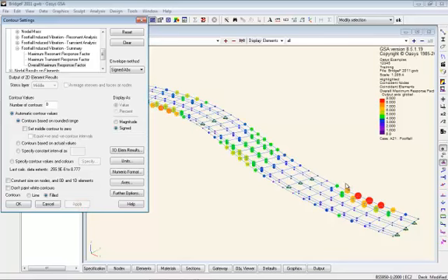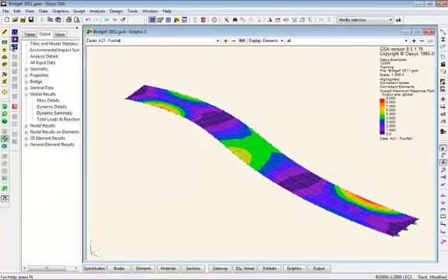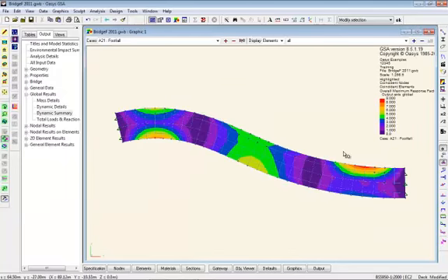Now this is the nodal results, which is right for us engineers to look at. If you want to show to the client, it's much easier to take these results and smear them onto the 2D elements. So if I look at the nodal results on elements, you then get a nice, easy to understand contour plot of the response values over the structure, and we see edges, not surprising, are the most crucial area. Haven't much time to go into too much detail. We will be looking at this later on in the year.